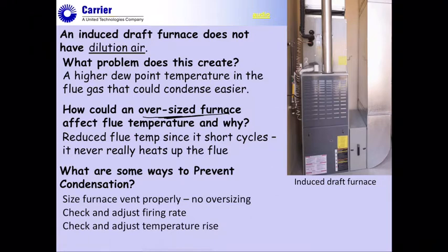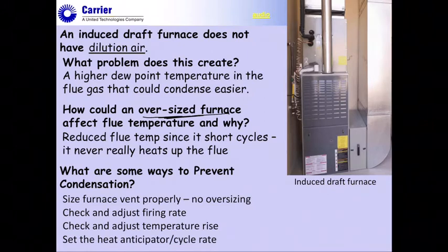So maybe you have to make sure you have your fan speed adjusted appropriately. And these are, again, I have to speak in terms of new and old. So an older application, these are things that you'd kind of expect to have happen, and you hope you can correct them on these service calls. And then, of course, you might have a cycle rate adjustment on a thermostat. That could maybe help you a little bit.